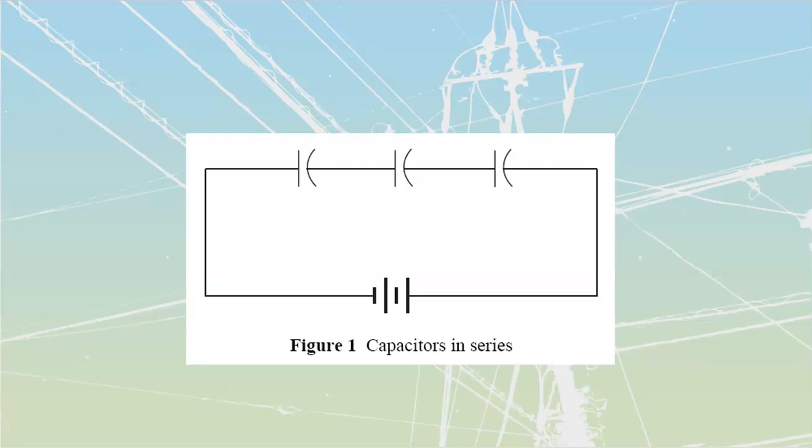First of all, before we do anything else, we're just going to take a look at my DC supply. We'll change that around, put that into the proper polarity. And now that we've got that into the proper polarity, because we've got polarized capacitors over here, we'll look at what happens when we close in on a circuit like this.